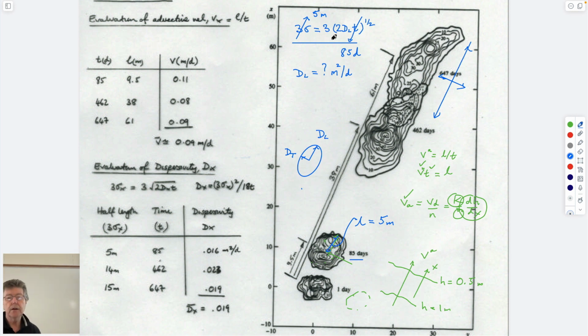In the advection-dispersion equation, some of the things that we took for granted was that we get plug flow and the arrival time is exactly equal to the length it travels, governed by the advective velocity and the time. Seemed to be a useful thing for us to assume, but it doesn't turn out to be true, especially for low Peclet numbers.